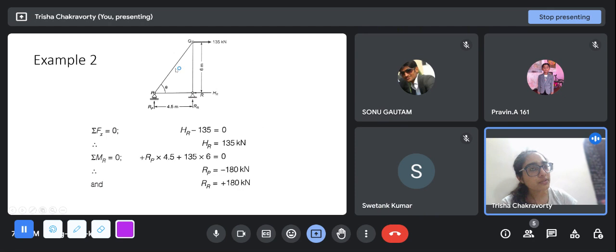If there were two or more forces applied on a structure, and you divide one of the forces by a certain factor, the member forces will not be divided by that factor. But suppose you have five forces on a structure and all five are divided by the same factor, like a factor of 2, then the member forces will be divided by 2. Basically you have to replicate the loading pattern exactly, and you need to conserve the ratio between the forces.